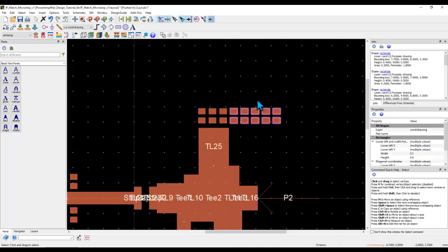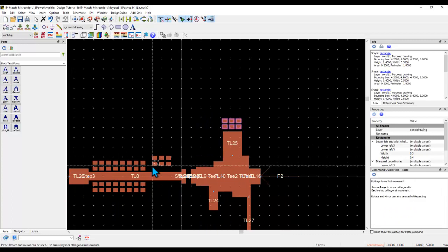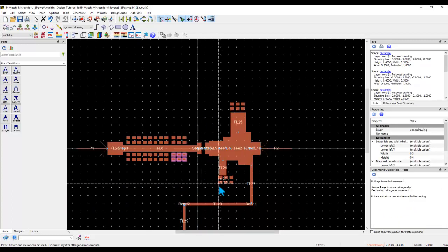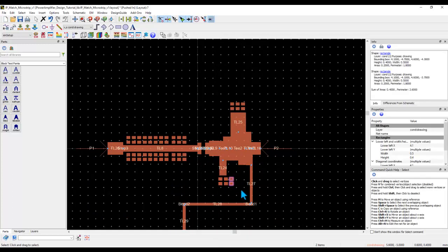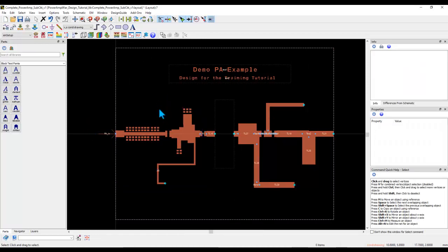It's all your choice. All right, so let me delete some of them. And again, I want this to happen across the length, so I'll also copy paste. And same thing you could do here. You can keep a couple of rectangles against that stub. So now at least you will have some flexibility of changing the impedance of these lines, and effectively you know what you're changing: inductance and capacitance and so on.